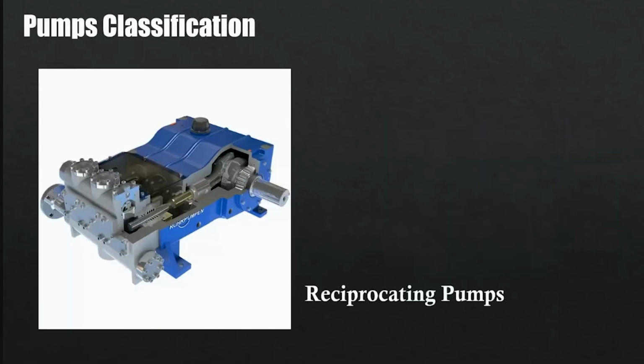The next is the reciprocating pump. It is a positive displacement unit wherein the pumping action is accomplished by the forward and backward movement of a piston or plunger inside a cylinder, usually provided with valves.